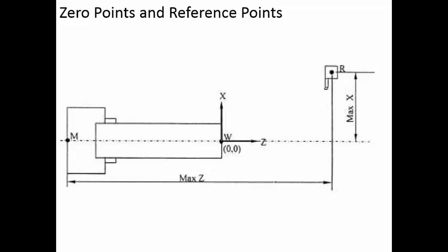So always we have to remember that we have to specify the origin of the workpiece, so that any operator who wants to machine that particular component will know where exactly the origin is. Whether it is inside, whether it is outside, or wherever it is, that has to be properly indicated. So that is another important thing to remember while we are doing CNC programming.